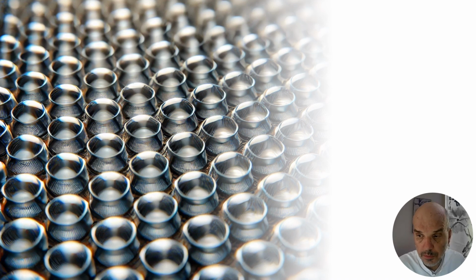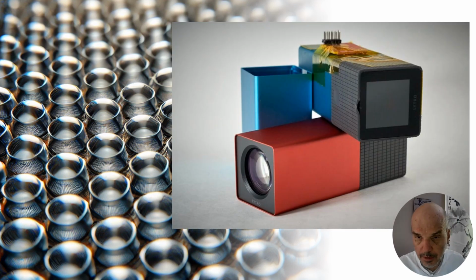The core issue is, what should the granularity be? How should you design lens arrays and lens hierarchical systems to process the field and fully capture the field most effectively? Here's one approach to that. This is the Lytro plenoptic camera, which uses microlenses in front of the focal plane to get some diversity in the sampling. This particular approach is not adaptive and gives up a lot of transverse resolution, really for no reason, because you can capture the same information with intelligent adaptive sampling.